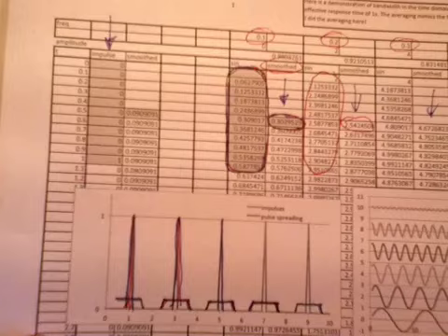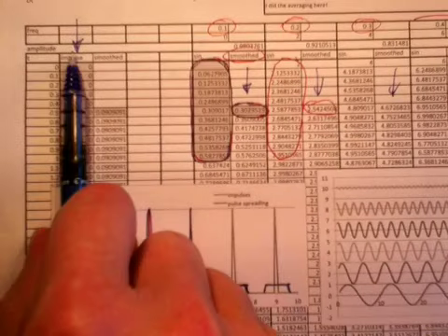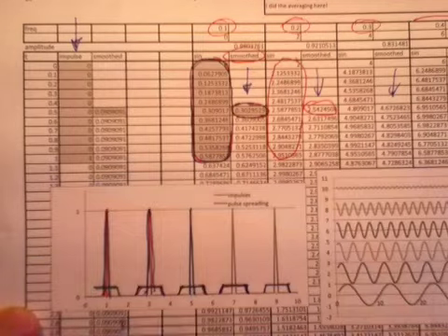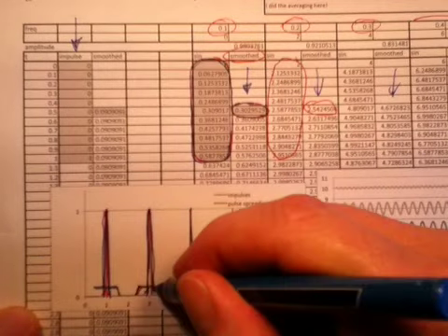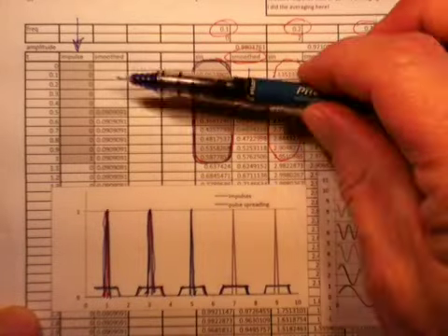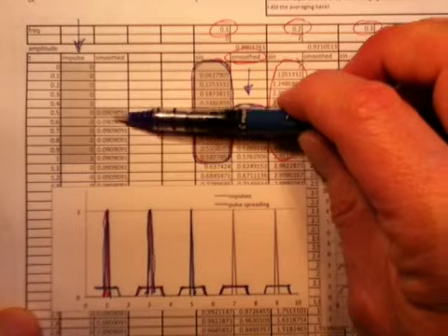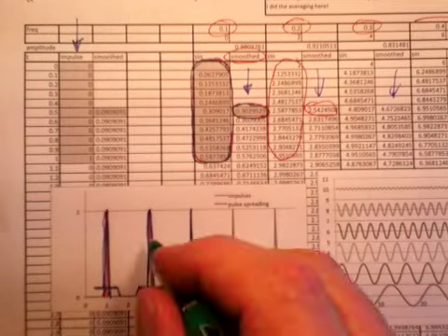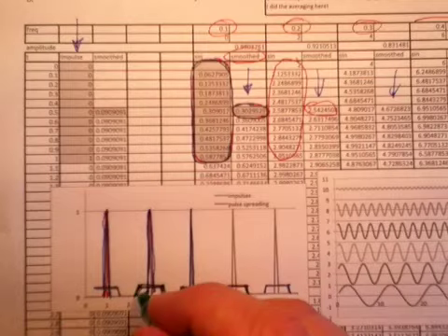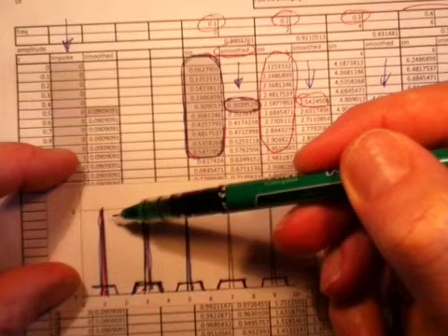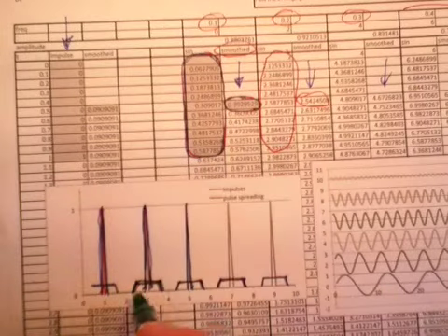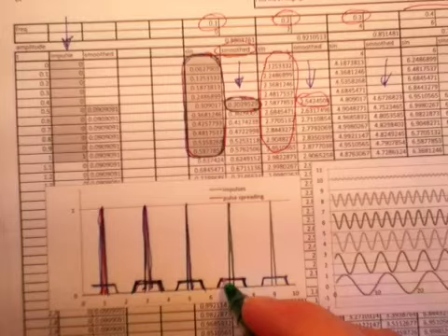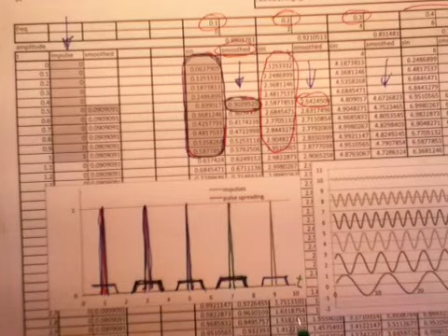I've also shown here in the plot, I've got my time axis, and in the second column over, I've got impulse responses. I've got a whole bunch of zeros, then a 1, a whole bunch of zeros, then a 1. You can see those pulses plotted as these spikes here in this graph. I also show the smoothed version of that, where each point is the running average of the points in its vicinity, and this shows explicitly that these spikes are spread out. So this running average, or boxcar average type of calculation, really does represent a pulse spreading type of phenomenon. You can see that these sharp pulses are now spread out in time in this spreadsheet.